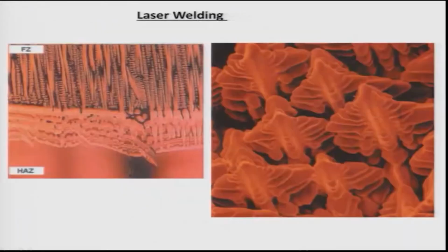All these industrially important processes require you to understand solidification. You see here the different zones of the weld. This is the fusion zone, in which you form certain geometrically important features known as dendrites.